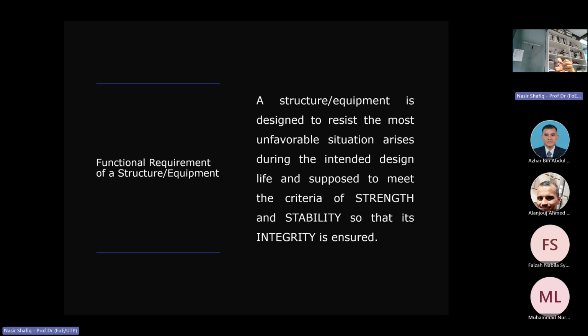That might cause elongation, cracking. So the material properties and the geometry of the shaft matter. First of all, it may bend because of poor geometry, so it is not stable. Second, it can crush, it can crack, which means its strength is not sufficient, right?